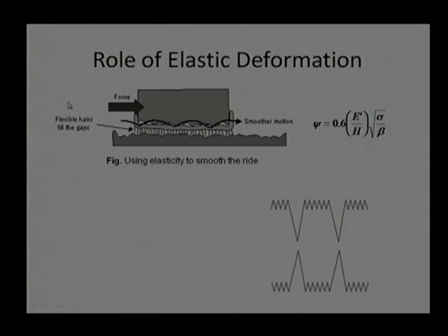That means if we are able to keep a low plasticity index, either by means of Young's modulus, hardness, surface roughness, or any combination of these, that will be a good option for us to increase the life of the component. One of the easiest methods to achieve a low plasticity index is to use a third substance between two substances. Let us take this example. Here we are showing the force pushing one component.